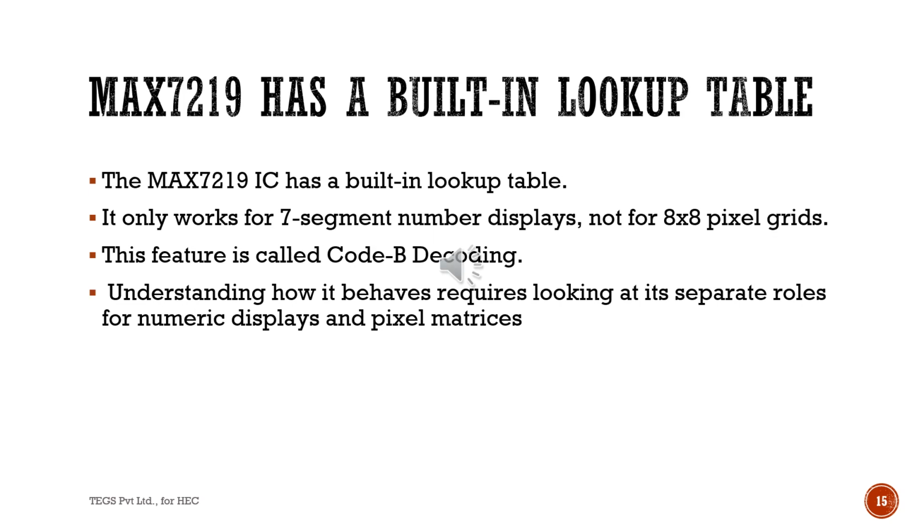Does the MAX7219 have a built-in lookup table? The MAX7219 IC has a built-in lookup table, but it only works for 7-segment number display, not for the 8 by 8 grid matrix. This feature is called Code B decoding.